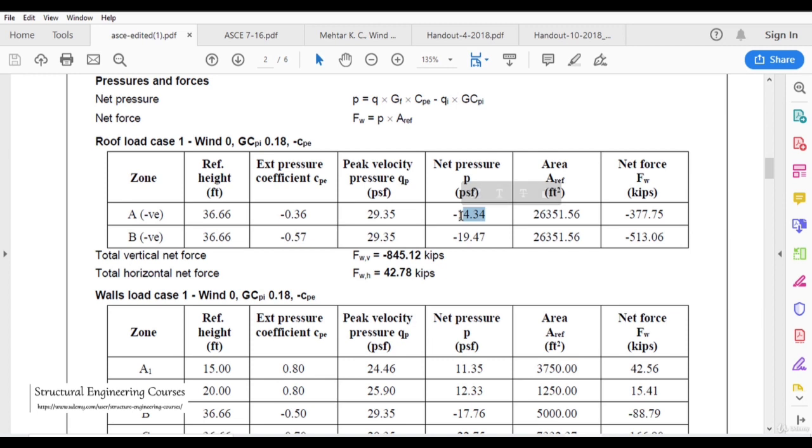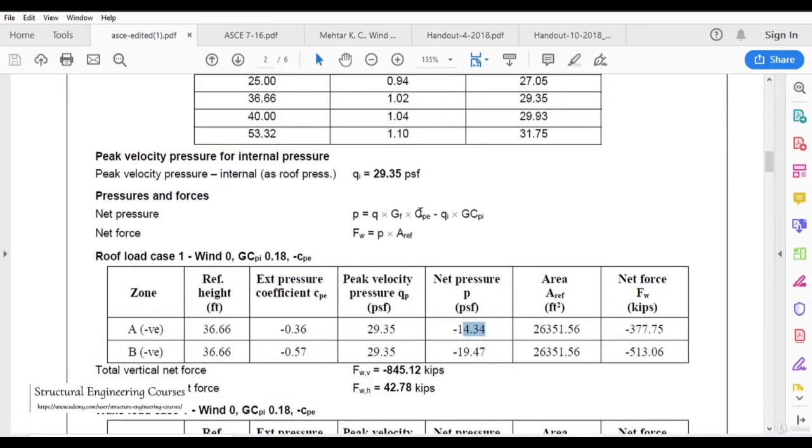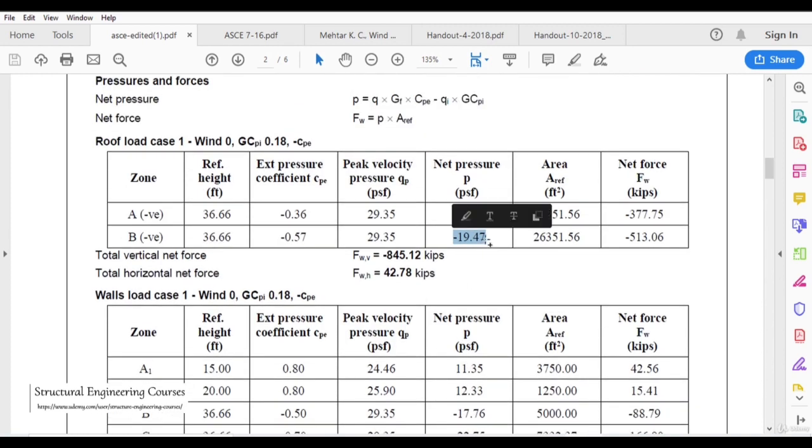We basically need to enter all these relations in the formula here, so that we can calculate the net pressure P. Both of these pressures are acting away from the structure, and these PSF values, when we multiply with base spacing, give the loading in PLF, that is UDL, that we can apply on the beams.